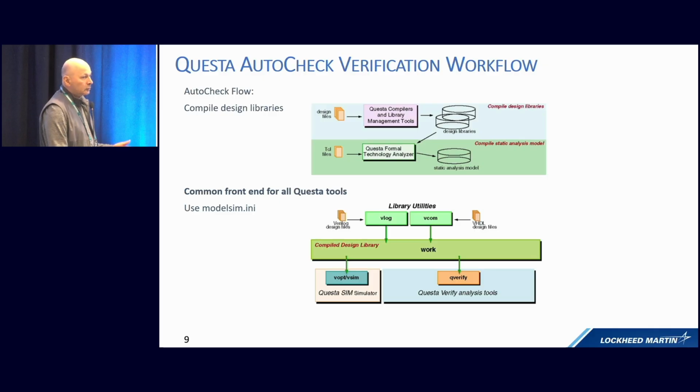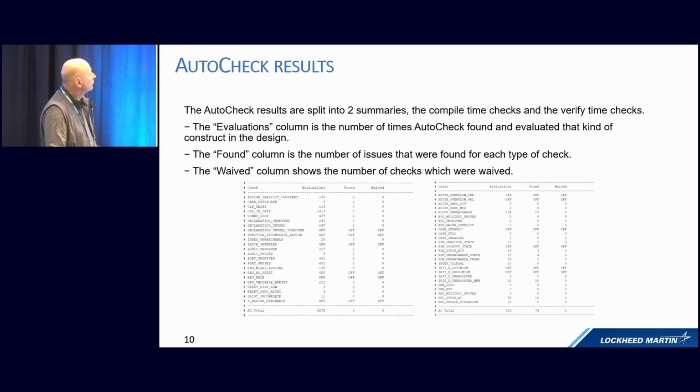So as soon as we have a design that compiles correctly, we're going to use the same compile to start AutoCheck. vlog, vcom, we get a work library, and we can do either the simulation or the Questa verify for AutoCheck. So the very first step is the same, and as soon as we can compile, we can run AutoCheck.